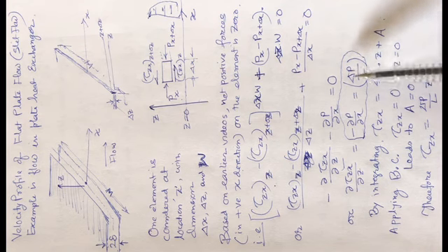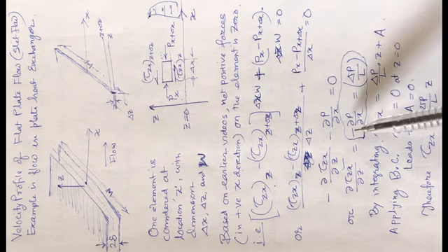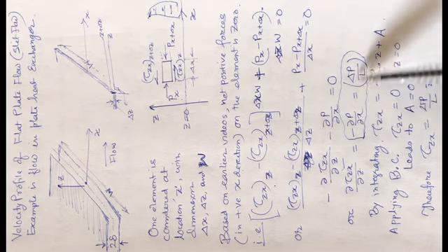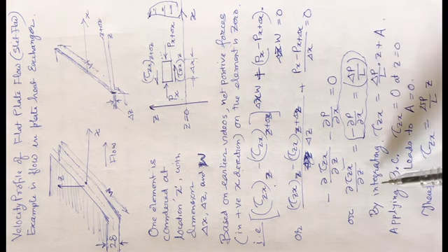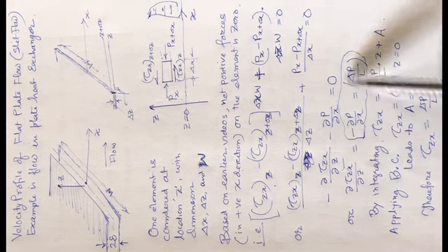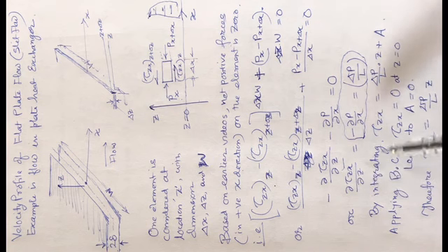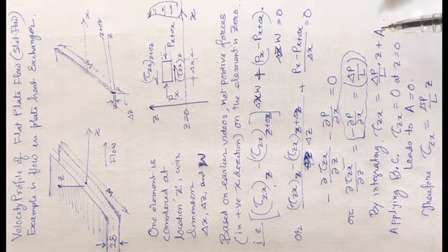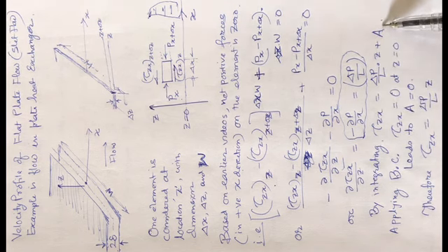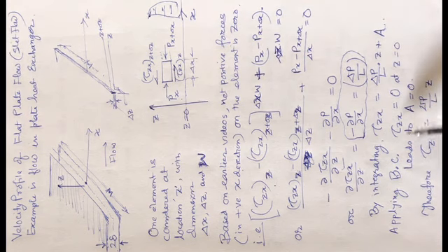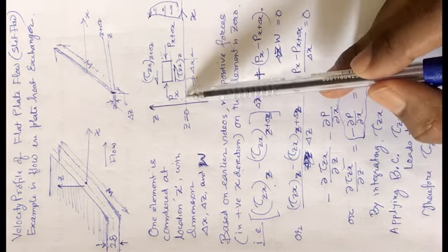However, the numerical value of delta p by L, you will see that geometrically or mathematically it will be a negative value. Okay, so now we are just simplifying this, because they are constant terms, we are writing delta p by L. So now we can integrate by separating the variables. Then we get tau zx is equal to delta p by L into z plus A, again a constant of integration. So now the boundary condition is applied: tau zx is equal to 0 at z is equal to 0, meaning there is no shear stress.